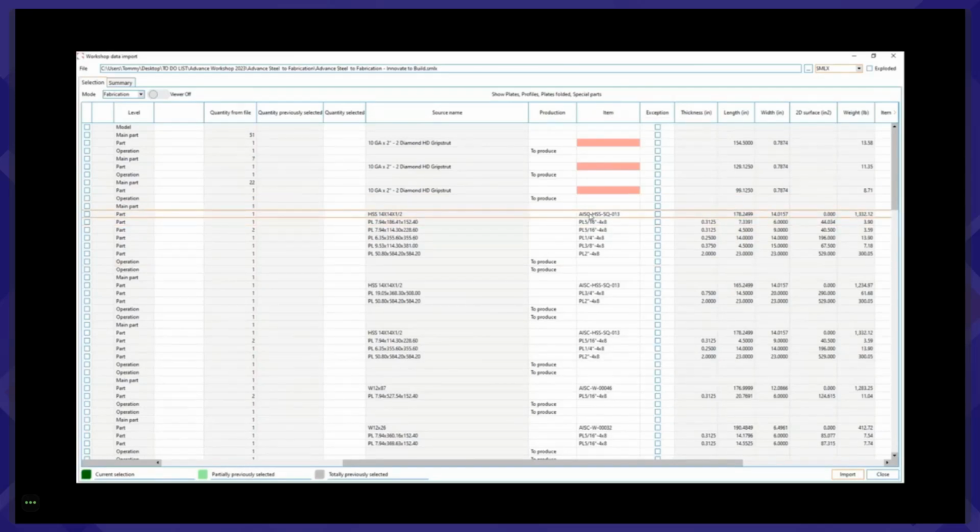Okay. Now, it's done in association automatically to items or SKUs within Advanced Workshop. So we have a mapping mechanism which will save entries. So once you've linked a part component to a SKU, when I say part component, I'm talking about the general section type and plate thickness, etc. Once you link it to a SKU, it'll create that preliminary link for future use. Why I call it a preliminary link is, of course, because when you go through the exercise of nesting in your database, you can have different SKUs that you would order from your suppliers that could be of different lengths.